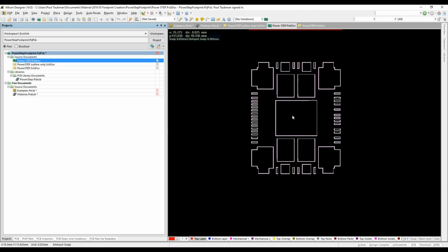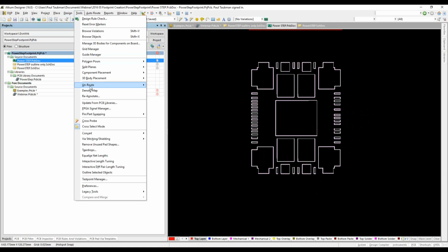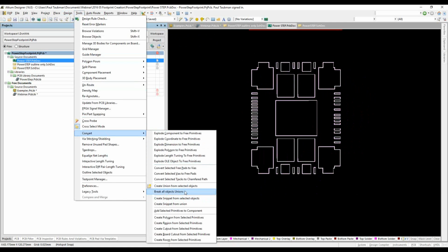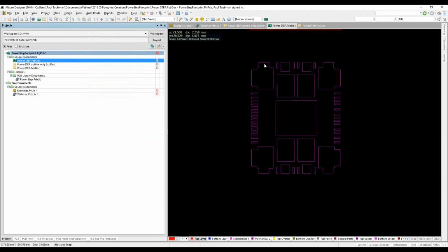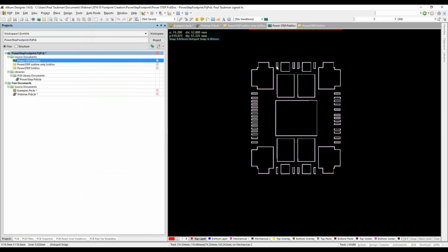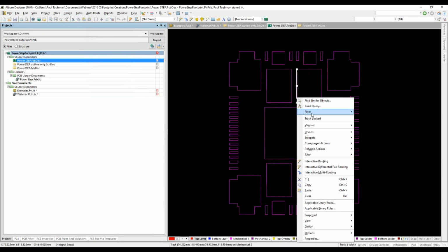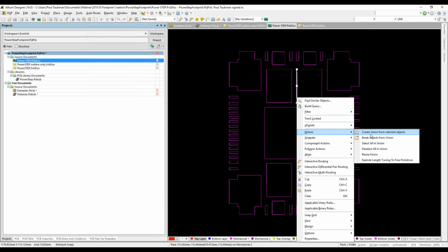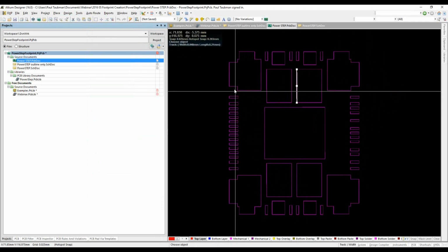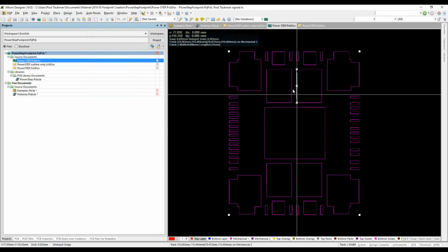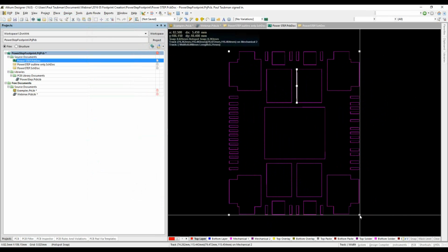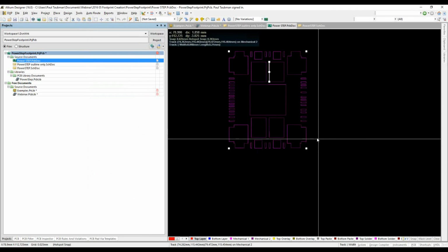If you're doing DXF DWG, you bring this in, it's not the right size here, then what you can do is you can always go into Tools, you can do a Convert, and then you can create a union from the selected objects. And once you've got these as a union over here, if you select it again, it's a little cryptic how you do it, but nevertheless, if you right-click on any one of the representations that are in this union, you can say resize the union, okay? And now it's going to ask me to select a representation of the union again. Now it's got the entire union, and as long as I click and drag it, I can move this thing to where my heart's content.